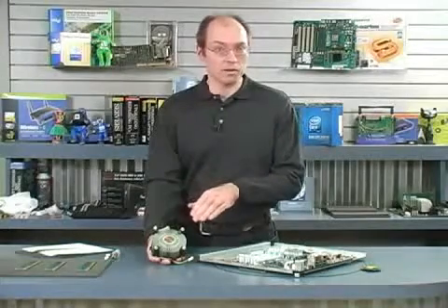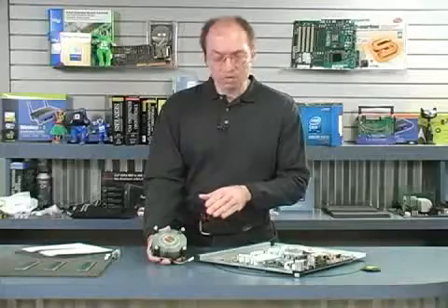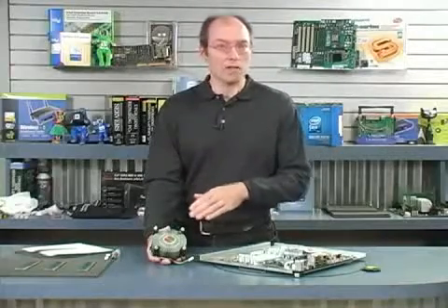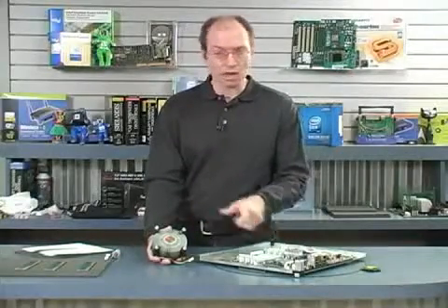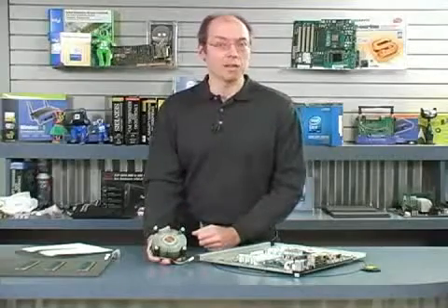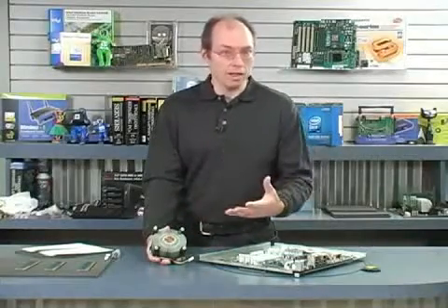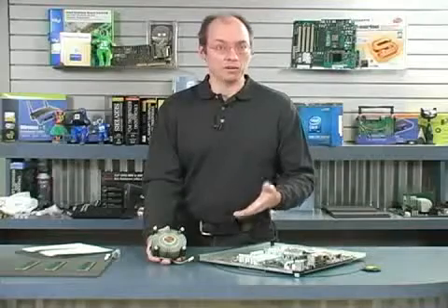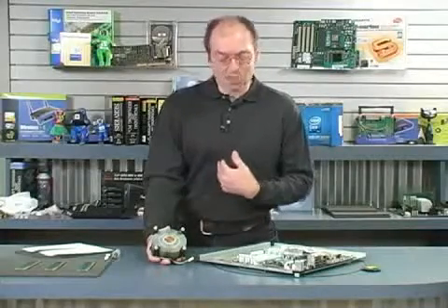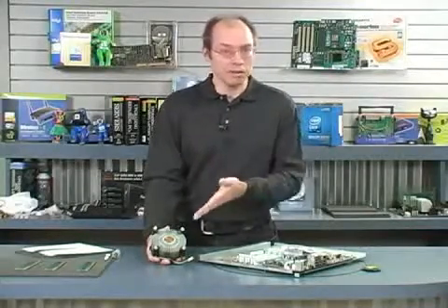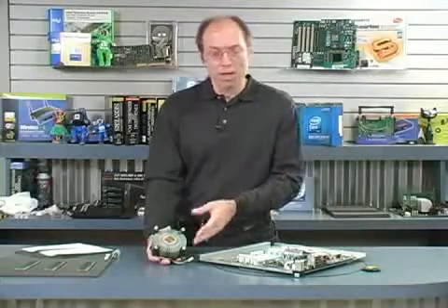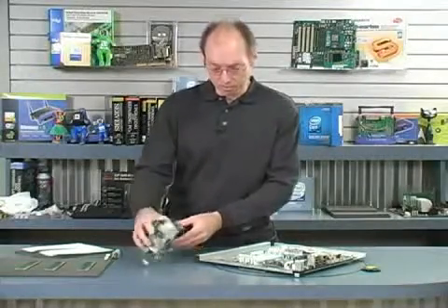Usually you can clean it off with a paper towel. Sometimes you need alcohol to help dissolve all of it. You want to clean it off the top of the processor and the bottom of the heatsink. Every time you reinstall a heatsink, you need to use new thermal interface material. And since, as an individual, I can't really get the phase change stuff, the only way you get that is pre-applied, we have to use what's called a thermal grease.